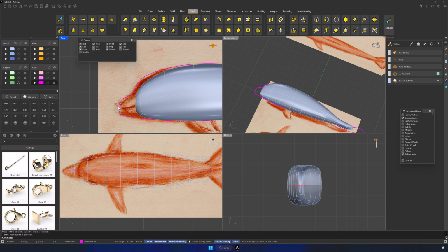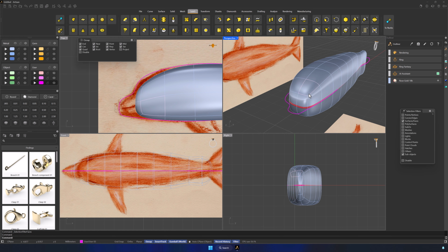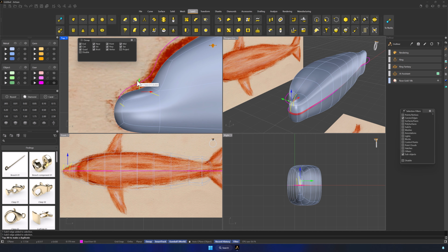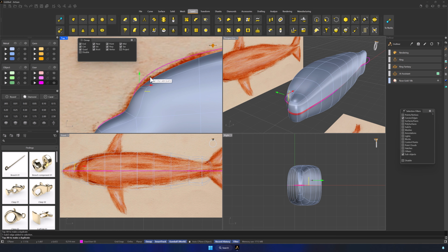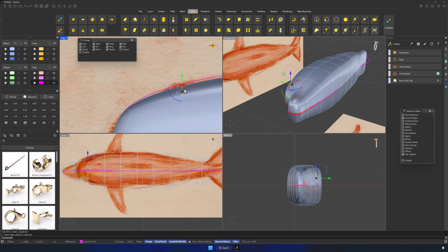Focus on the dolphin's head. Start by extruding a face. Since Reflect is active, any changes on the lighter side will be mirrored. Use the gumball to adjust as needed. Use all views to get multiple perspectives and better accuracy. Take your time and pause if needed.